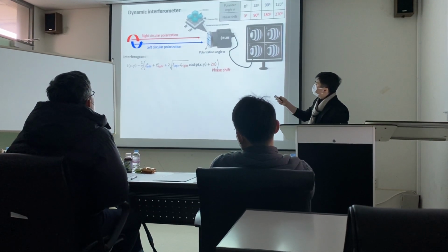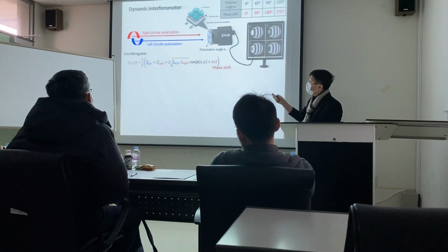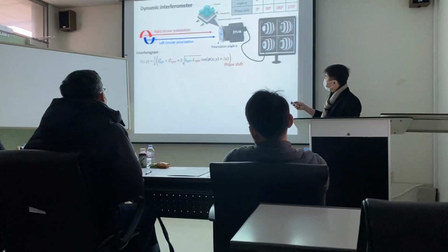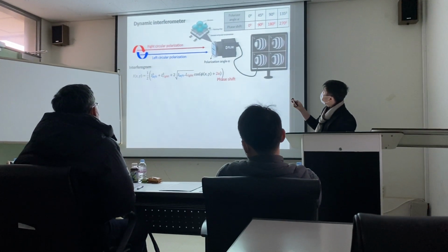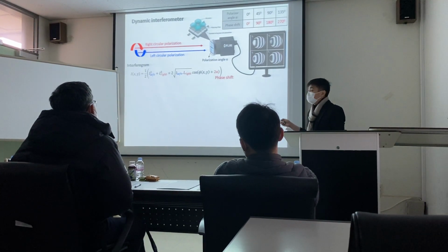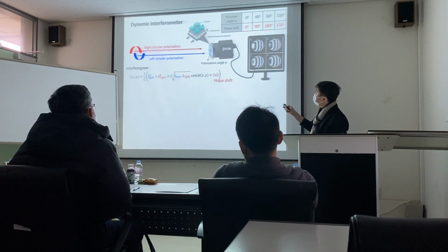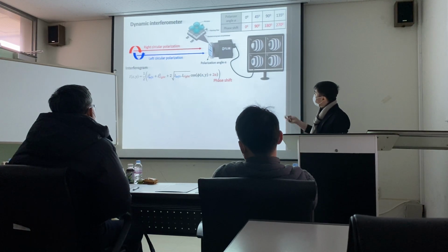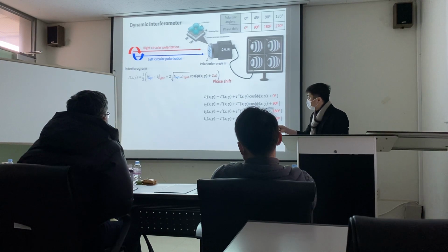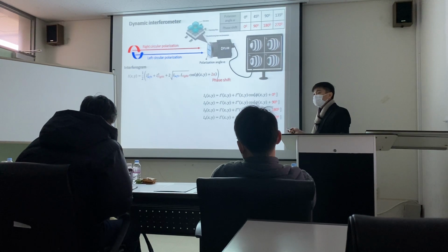In the design of the camera, they make linear polarizers at 0, 45, 90, and 135 degrees, and we get phase shifts of 0, 90, 180, and 270 degrees, respectively. These give four interferograms, I1, I2, I3, and I4. The mathematics represent the four interferograms I1, I2, I3, I4 with phases differing by 90 degrees.